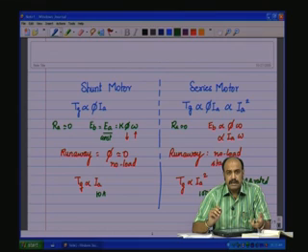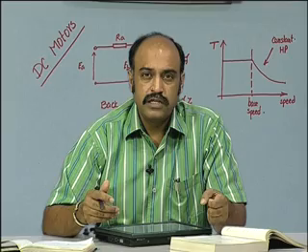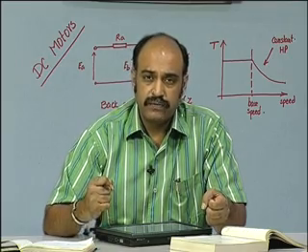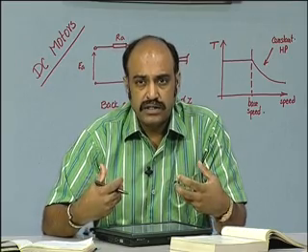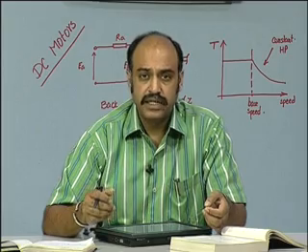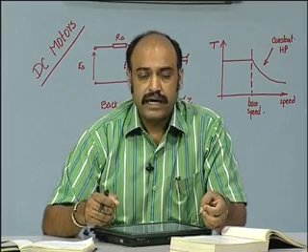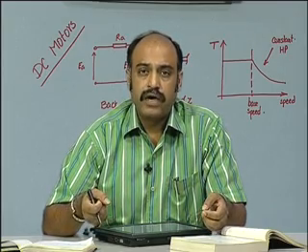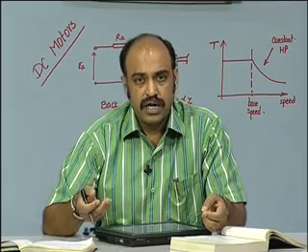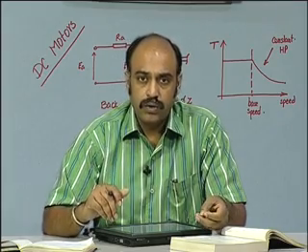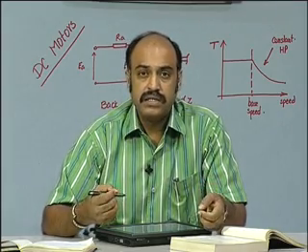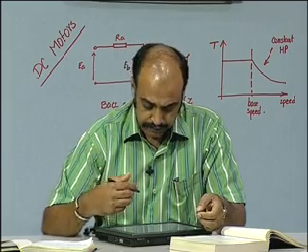Now, some such applications would be like in traction, in electric traction. A series motor will be able to generate a very high torque in overcoming the initial inertia, or in cases like cranes, where it may need huge torques in lifting a particular load. Now, these are applications where a series motor would be ideal.